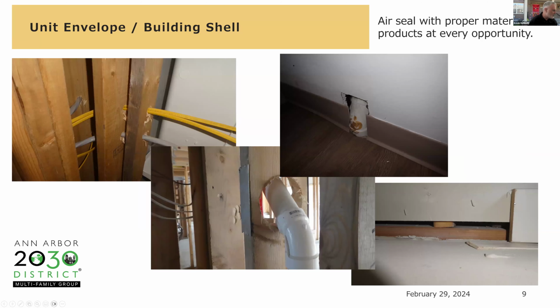Okay, trim is fastened to the drywall and it's being held a 1/2 inch off the bottom plate of this wall assembly here. So we would need to either seal the drywall, this gap here, or seal the gap between the trim and the bottom plate. And you can use backer rod or a foam gasket of some sort there.